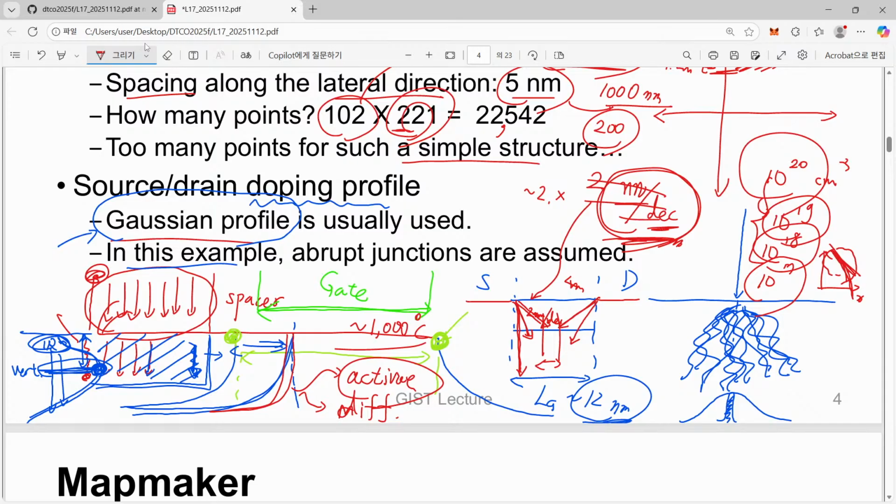And nowadays, even this seconds-long anneal, called rapid thermal annealing, seems to be too long, so nowadays we are using a laser to anneal our source and drain. The laser can be controlled for a much shorter time. When exposed to the laser beam, the atoms gain certain energy and take the desirable position.